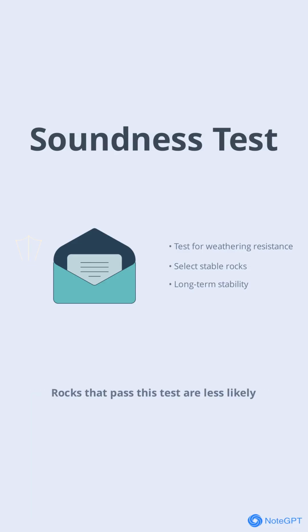The soundness test evaluates the ability of rocks to resist weathering and chemical attack. Rocks that pass this test are less likely to break down or lose strength over time. This is particularly important in environments where the fill will be exposed to water or chemicals. Soundness testing helps to ensure the long-term stability of the structure.